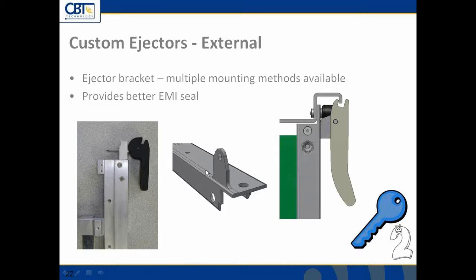So it's really positive from that standpoint. Very structurally sound as well. And then, of course, the ejector mounting method can be a bunch of different ways. We'll talk a little bit about that too. And then this customer here had a little die cast block on the end, which then the plastic ejector, in this case, was just mounted to that with a roll pin, and that worked out well for them too. So a lot of different ways that this can be done.